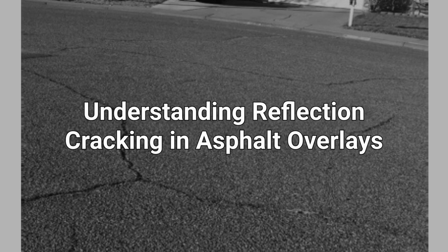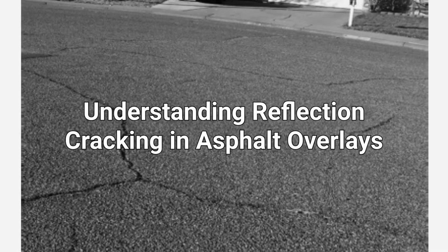Understanding reflection cracking in asphalt overlays. Definition. Reflective cracks, Fig 8, are cracks in asphalt overlays reflecting the existing cracks in the underlying pavement before the placement of the overlay. These cracks are larger than block cracking and can be longitudinal, transverse, or random, depending on the pre-existing cracks in the underlying layers. Causes. Reflection cracking occurs due to stress created by the horizontal and vertical movement of the underlying pavement structure, following the fracture mechanics rule.